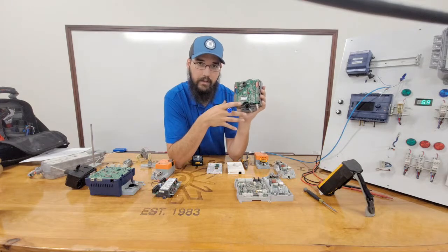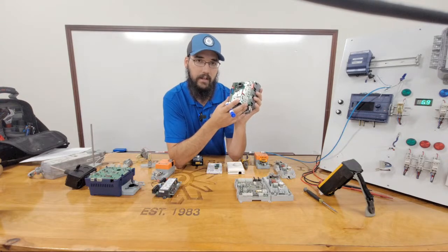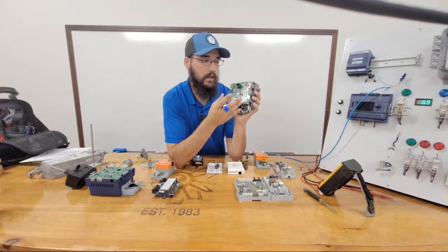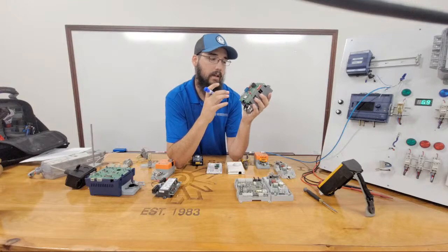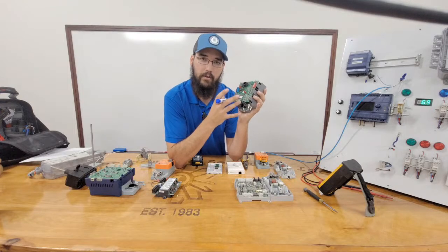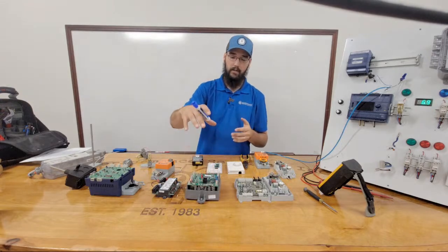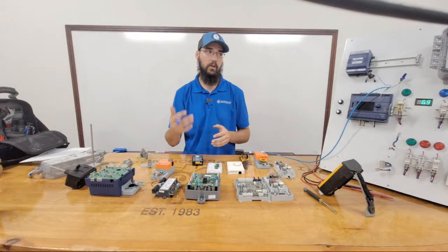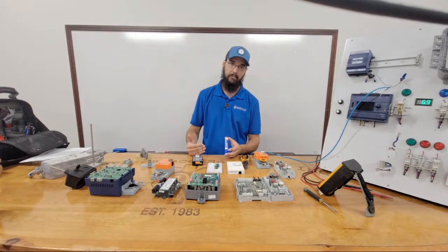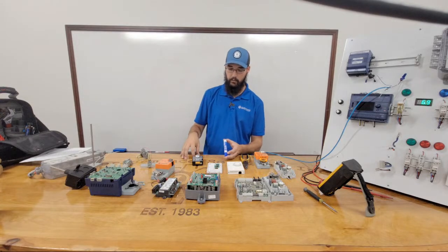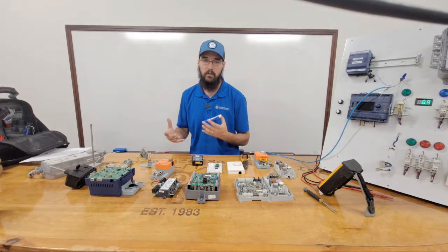I'm not going to go crazy into all the little nuances of this. My point is just to give you some understanding of what this looks like and the differences. The biggest thing that's different about modern controllers versus a lot of your older style is that these cannot handle loads. A lot of older controllers that had legitimate relays in them had the capacity to support some kind of minimal load through there.